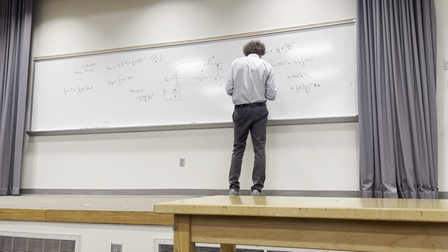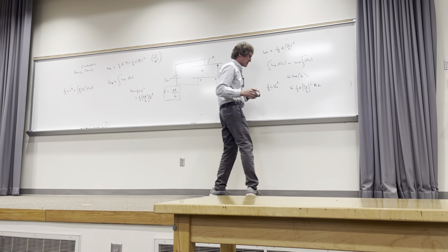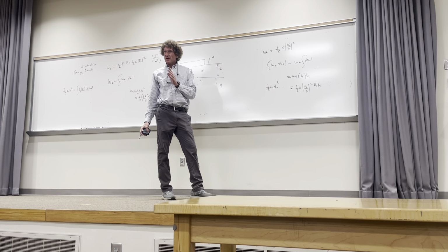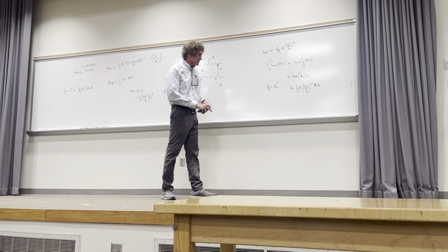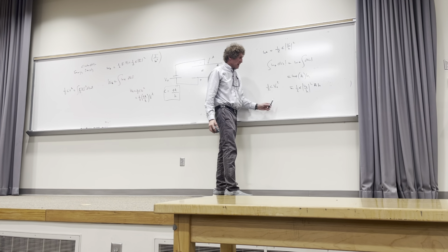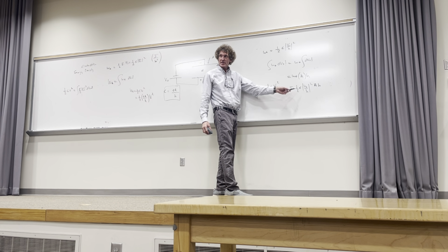And that's equal to 1/2 C V naught squared. Now, do y'all see what I've done there? I used the E field that I got by assuming a voltage, and now I'm calculating the total energy in that system. And I'm going to get the capacitance this way. Now, y'all see that V naught squared cancels, don't you, class?